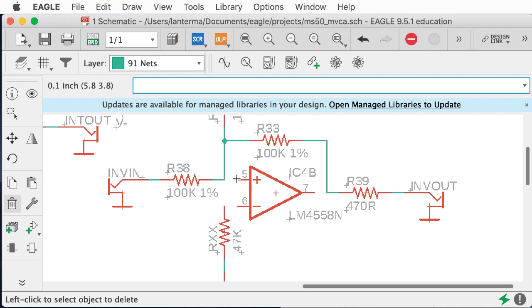Many moons ago, I worked on a circuit. It was an adaptation of the balance modulator in the Buchla Music Easel. And there's 12 op-amps in it. I used 6 dual op-amp chips. And I sent it off to get manufactured. And then later looked at it and realized I had the plus and minus switched on every single op-amp. I did build it as a prototype. I wound up bending the pins upward and using wire wrap to cross as it went into the board, but that was a deeply painful experience.